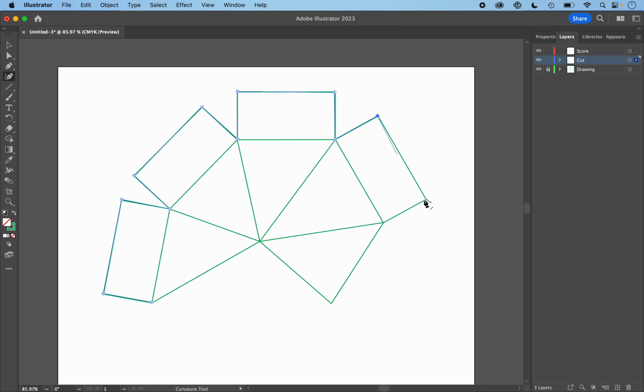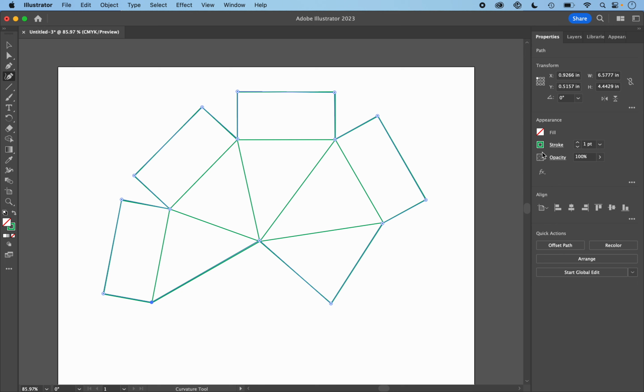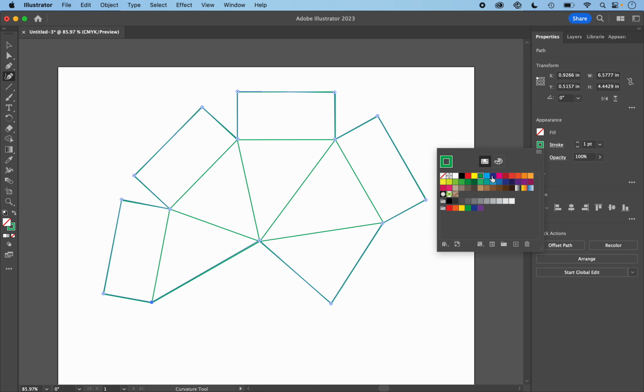And we're just working our way around the outer perimeter so that our plotter cutter can cut out this module for us. And then when we come here, you see how it's hovering and make a curve? I'm going to let go of Option. I'm not holding it anymore. When I hover here, it gives us that little circle that says we're closing this shape, and we'll click and close. Right now, though, this shape is still a green. And so let's drop into Properties, and we're on the blue layer, and we're going to choose this blue that's CMYK blue. So we'll switch it over to blue.